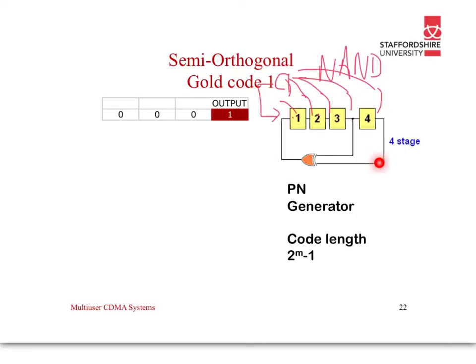So here if we've got a 1 here and a 0 here, then the exclusive OR to that would be a 1. The truth table for exclusive OR, as I've said, is 0,0; 0,1; 1,0; 1,1. So 2 zeros is a 0, a 0,1 or a 1,0 is a 1, and a 1,1 is a 0. We can have more than 2 inputs to an exclusive OR. If we remember the term, if there's an odd number of 1s, the output is 1. If there's an even number of 1s, the output is 0.